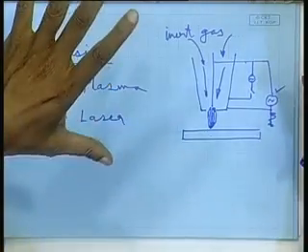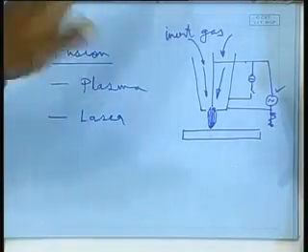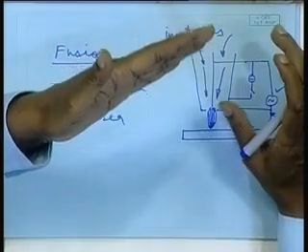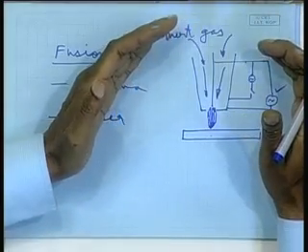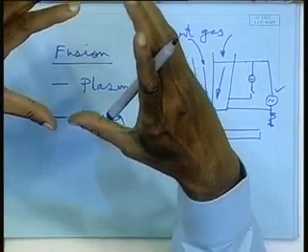But still oxy cutting is used heavily for the simple reason that its cost is much less. And at the same time, one will have to work out the productivity of each workstation depending on the overall productivity. If at one place I have a very high efficiency workstation, and the very next place I have a very low efficiency one, then in fact I am in trouble, because here I will produce more and that will get stockpiled. That is what is called bottlenecking. It will form a kind of a bottleneck, right.